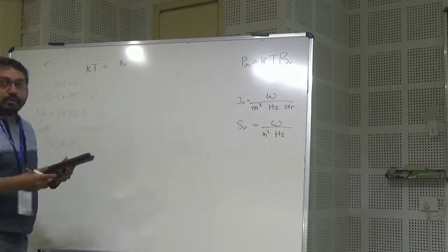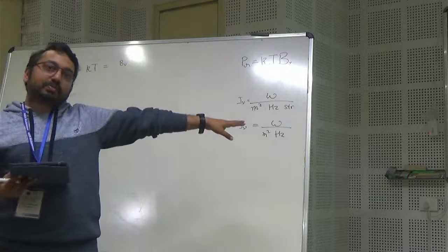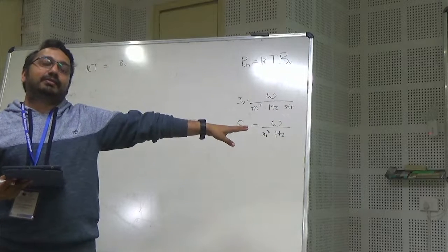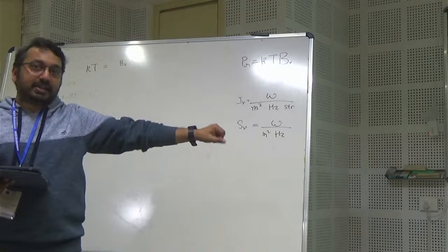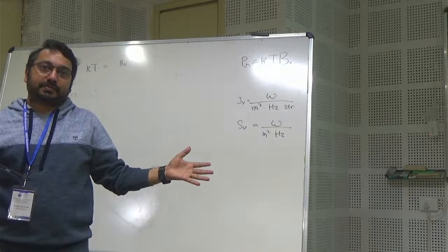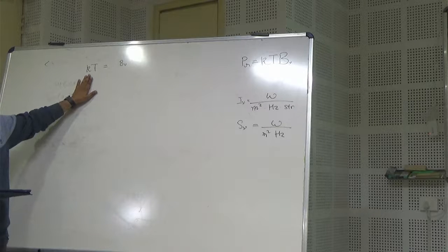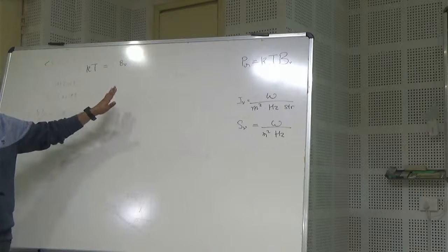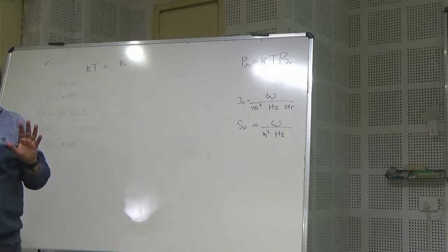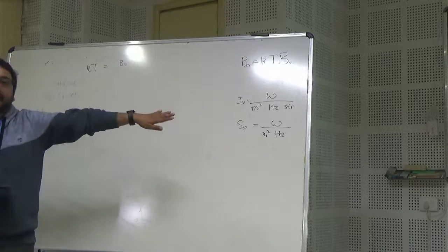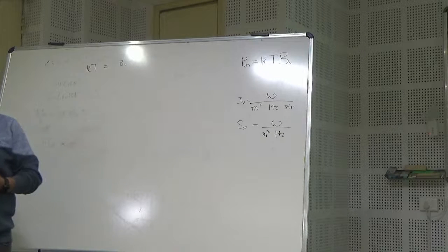Can you please explain that? This one. So I am equating the power in the resistor to the power measured by the antenna. Like, antenna is receiving power from outside? No, from the resistor. This is a closed system. So on one side, I am listing what is the power from the resistor, which is kT. This comes from Johnson noise. On the right side, I am going to write what the antenna will receive. It should be equal to kT because they are in equilibrium. Then through the wire. Yes. There's no radiation.